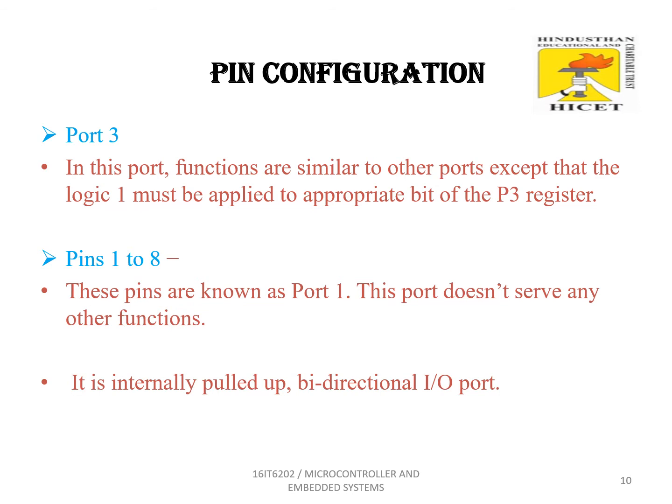So first take pins 1 to 8. These pins are known as port 1. This port does not serve any other functions. It is an internally built bidirectional input-output port. It just acts as the input-output port. Other than that, it cannot do any other functions.